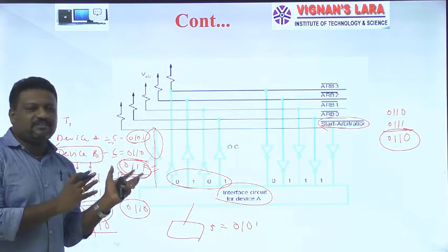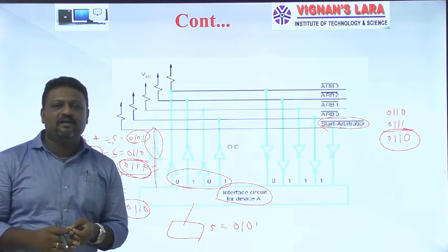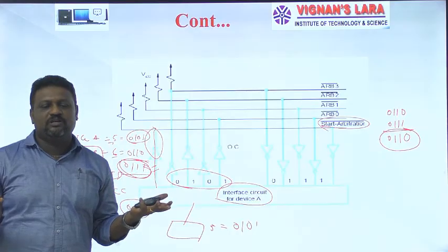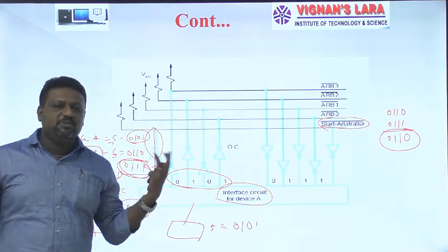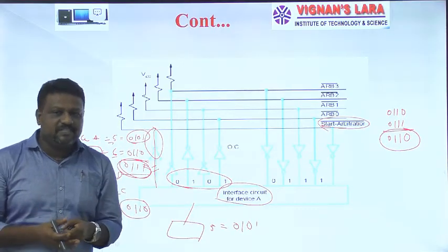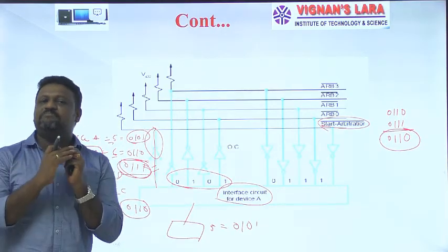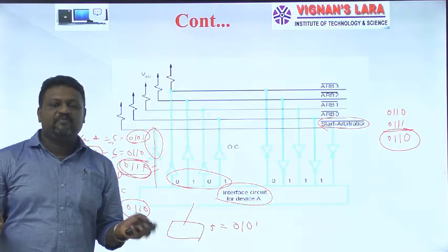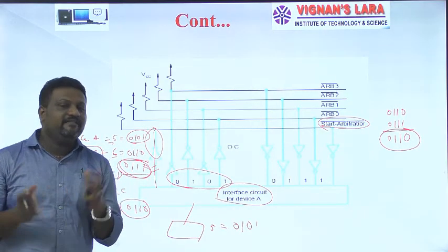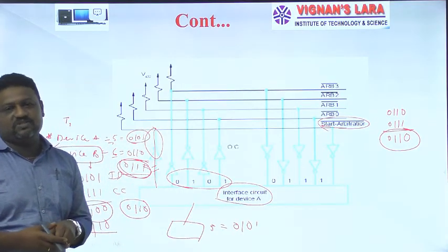If you think about it, guys, this is very simple logic. If a device wants to use the bus, it informs the rest of the devices. That means there is a discussion going on between the devices involved in the bus arbitration. Finally only one device gets permission from the remaining devices and that device becomes the bus master.